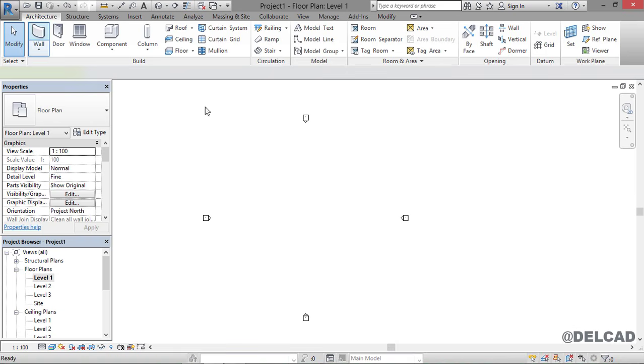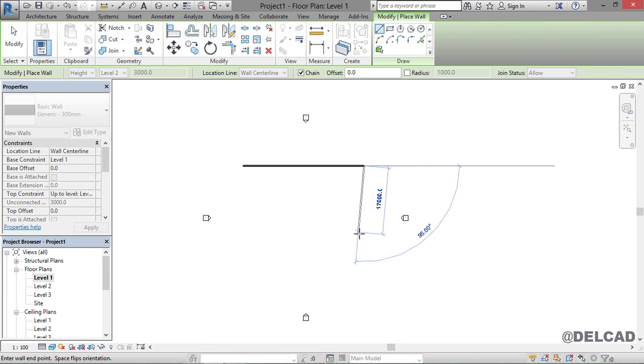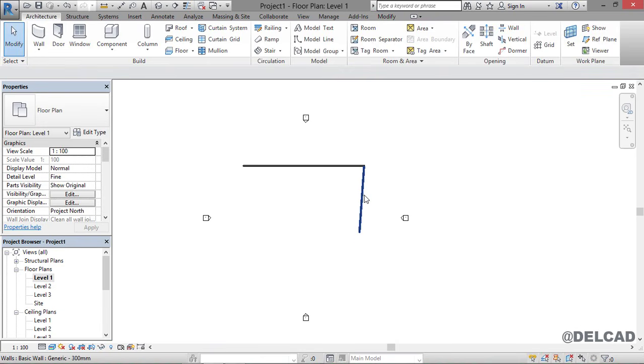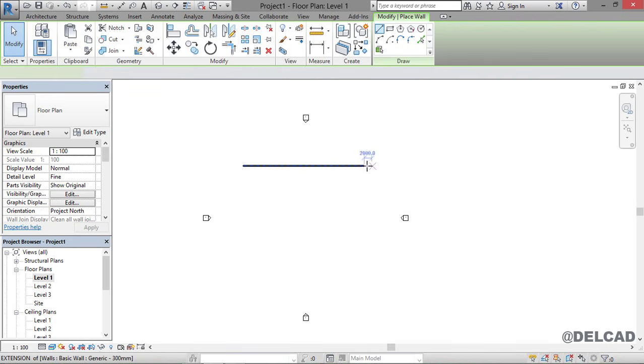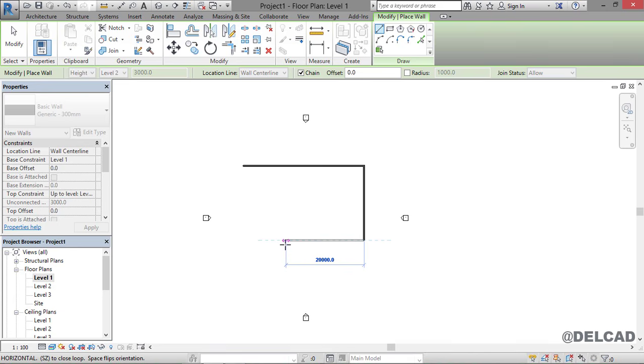Again, let's pick this wall and see how we can create a simple building. So we can click and drag to create a building like this. So we can click delete this, go ahead, pick the wall tool, and we can click here to create a building or a wall like this. We can hold the shift key to make sure that our drawing is orthogonal, so we can draw either horizontally or vertically